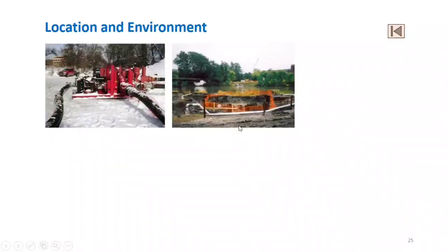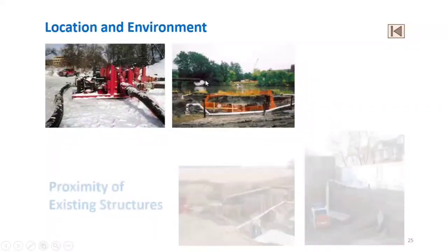The most important concern here is if you are going for a deep excavation nearby this river, you have a very big source of quick recharge. You are pumping out water from an excavation nearby to this source, so that source will be recharging the groundwater table very quickly. Very high flow rates towards the excavation can exist, and you have to have a very huge capacity of dewatering systems. So this depends on the location and the environment where you're doing your deep excavations.